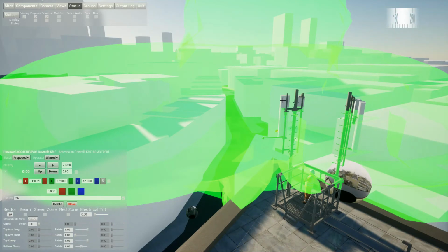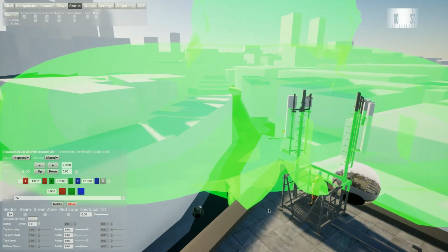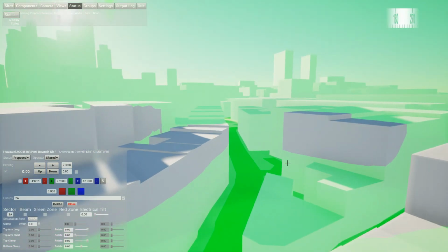So things we can look at are maybe the power assessment. We can look at the tilts. We can look at optimizing the power, maybe removing old technologies, for example. We can change the antenna type and adjust the height. And in a new build situation, we can look at an entirely different scheme, one that maybe will solve the problem. So we can look here, we can get a powerful example of just moving the antenna, or the antenna orientations.